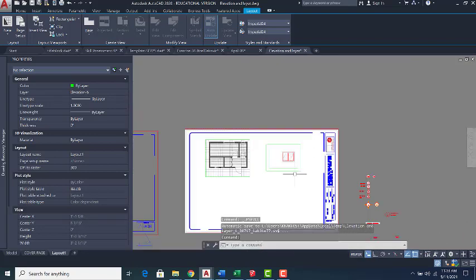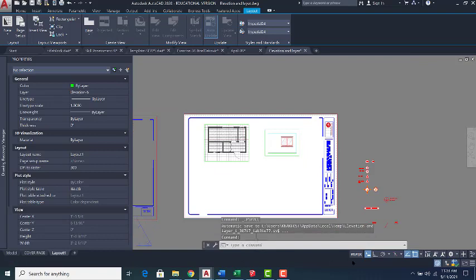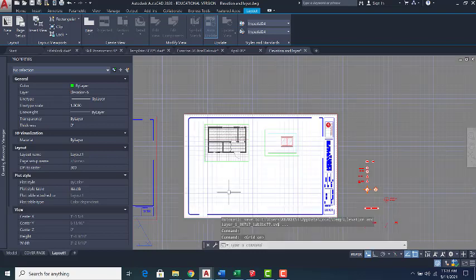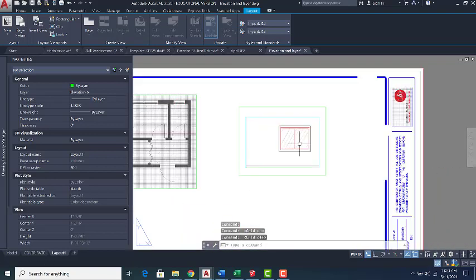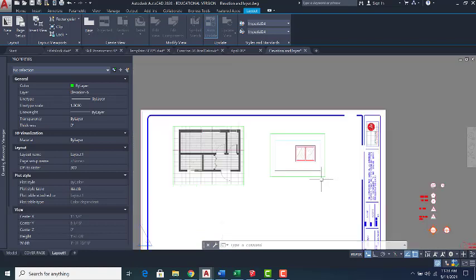If I deactivate the viewport and I go and press F7, see, it would add the grid to my screen here, or I remove it. So now I have my first elevation. Okay, I can again go here, insert a new viewport, or I can just copy this one.